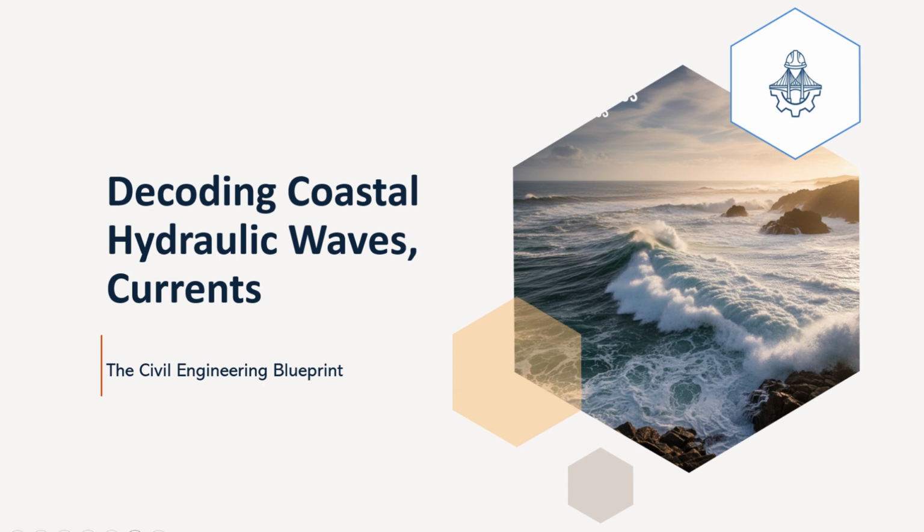Okay, and then to make it a solvable problem for our specific scenario, waves in a water basin of a certain depth, we need to apply some essential boundary conditions, right? These are the critical constraints that define the physical environment where the wave actually exists. Absolutely. These are non-negotiable physical constraints we have. The lateral boundary condition. We generally assume waves are periodic in both space, x direction, and time t, meaning they repeat their pattern predictably. The bottom boundary condition. The seabed is solid and stationary. There's no flow through it. So the vertical velocity component w must be 0 at the bottom, which we usually define as z equals -d, where d is the local water depth measured positive downwards from the still water level.